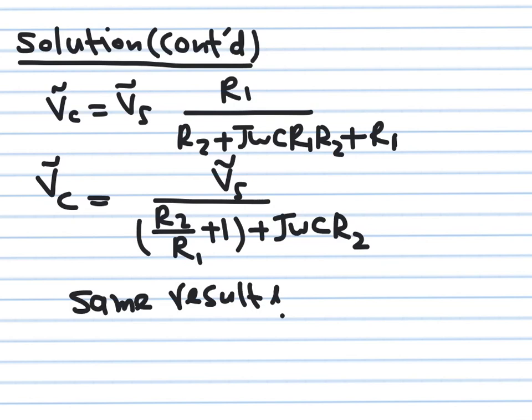I'm just looking a little bit ahead to show you that from now on you don't have to write the differential equation at all. You can analyze a circuit with 10 capacitors and 10 inductors with great ease by replacing the capacitor by its impedance 1 over j omega c and replacing the inductor by its impedance j omega L. And then you apply KCL, KVL, voltage division, current division, Thevenin, everything still applies, but all the results will be complex.